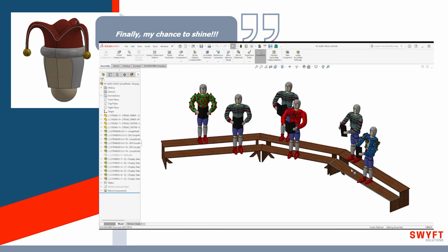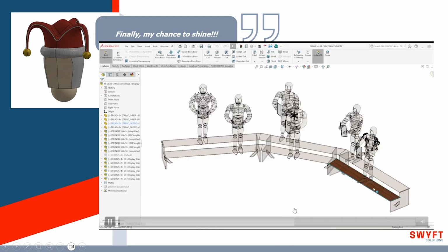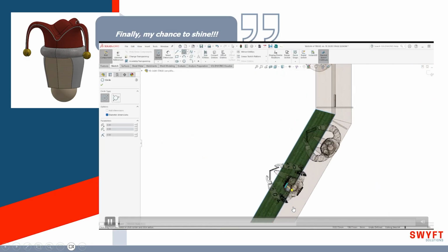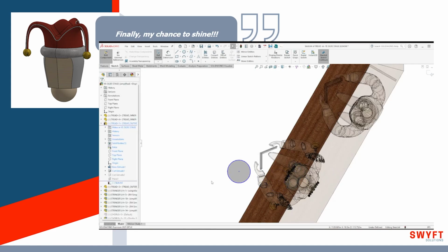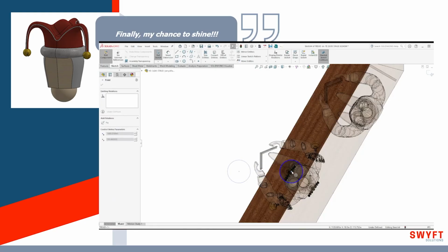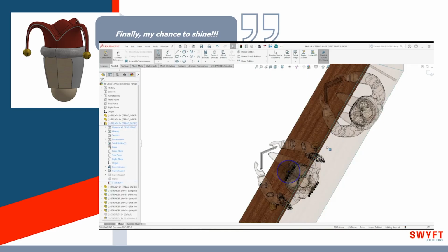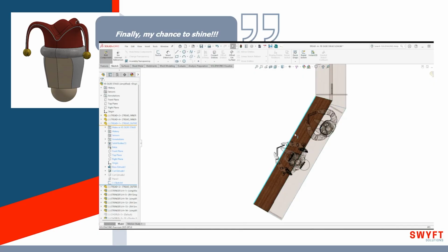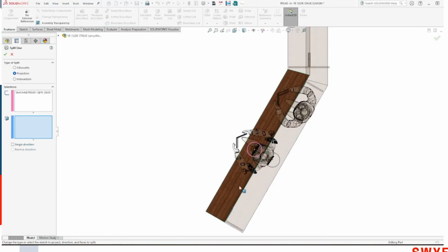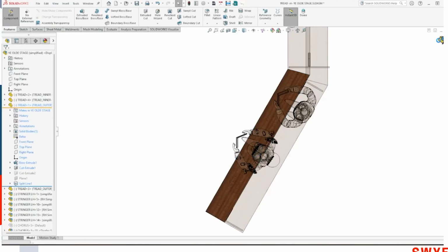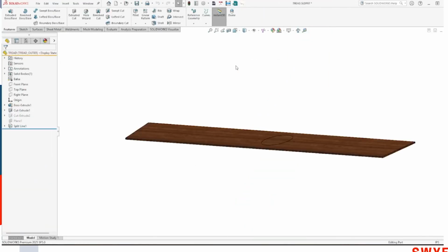And it looked like we're just going to let this keep rolling. Now I am assigning a circle here in the part, and I want to make sure that that circle isn't grabbing on to any references. I did that by pressing F3. So if you ever have a situation like if you're working with splines and they don't want to grab onto a point, and you press F3, you can create your spline and then you can just put it in wherever you want without any of those external references. Just make sure you press F3 again to bring it back.